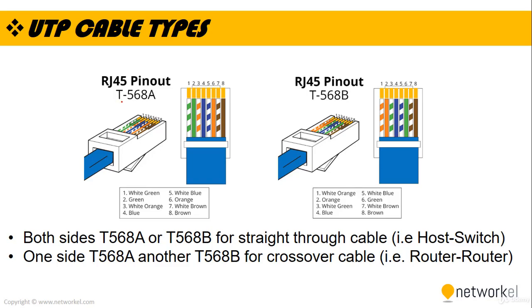Here, as you can see, the T568 pinouts, and as you can see, we have 8 pins in here. If you are using this pinout with T568A, in the first pin, you're using white-green cable, in the second you're using green, third white-orange, blue, white-blue, orange, white-brown, and brown.